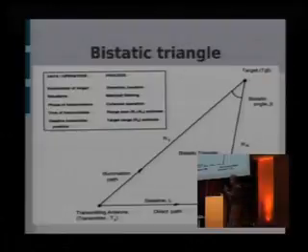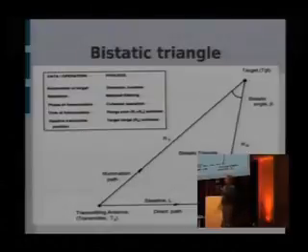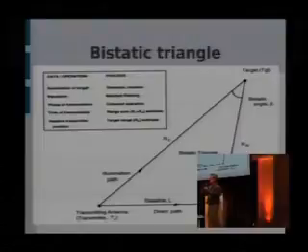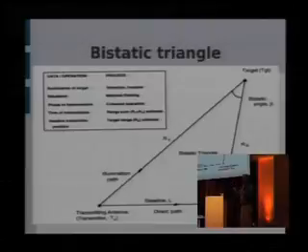The other thing to notice is the distance. Within the monostatic radar case, since the transmitter and the receiver are in the same place, you send this pulse, it goes out, hits the target, and comes back in. If you just measure that time of transit, it goes out and back, so it's twice the distance, and you know the path out is the same length as the path back. In the bistatic case, they're potentially different lengths. So you get this idea of distance, but it's not just one way.